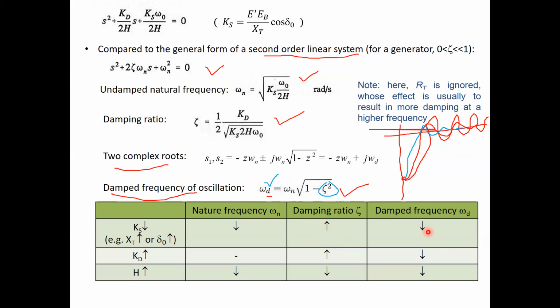Now, if you remember, maybe last semester or in the beginning of this lecture, we talked about a low resistive line and a highly inductive line. Because a long transmission line will be highly inductive, but the line in the distribution network is mostly resistive because the distance is small.